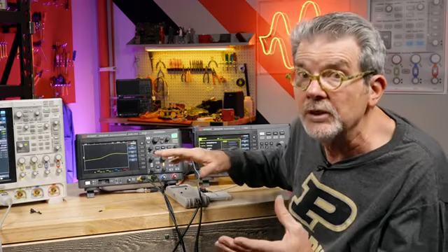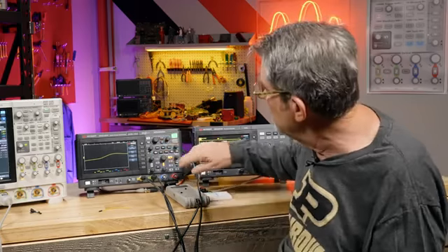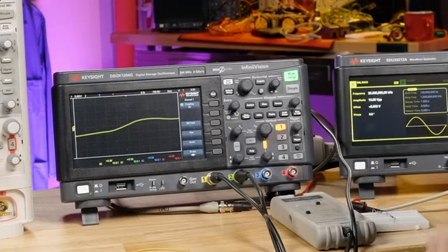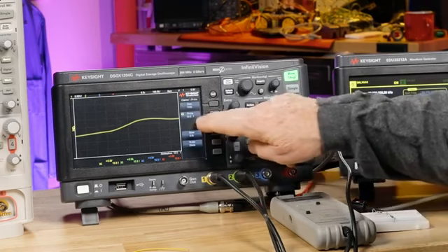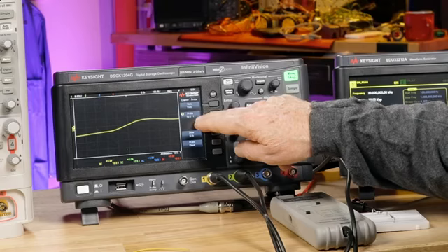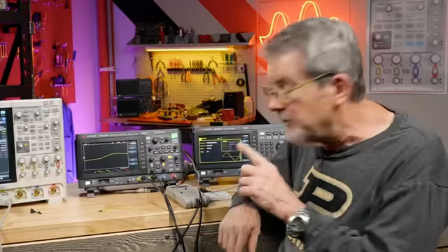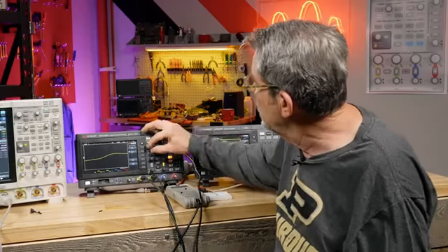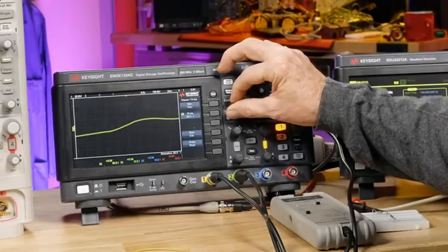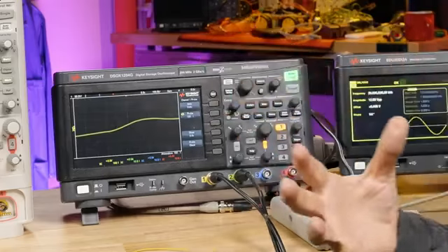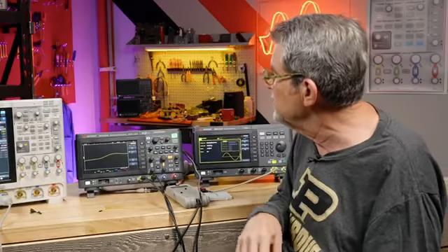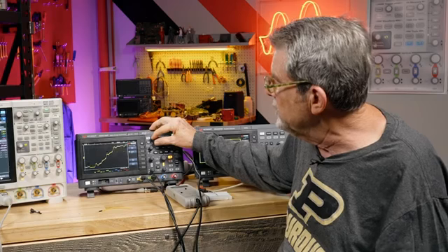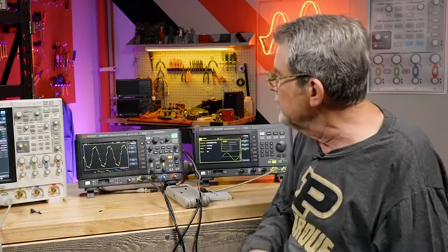is we need to tell the scope what the probe attenuation factor is, or the conversion factor of each of the probes. So I'm going to go into the Channel 1 menu, select probe, and you can see it says 10:1. That's where it was set the last time. I've got my high voltage differential probe set to 100:1, so I need to change that to 100:1 so all the measurements will reflect that level of attenuation. Then just set it up like we've discussed earlier.